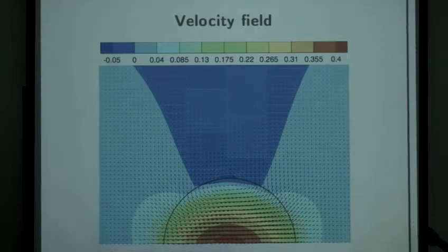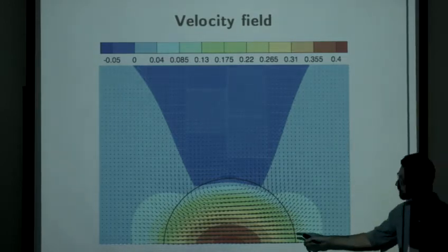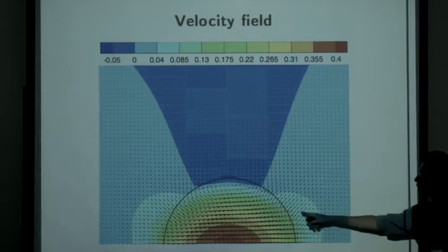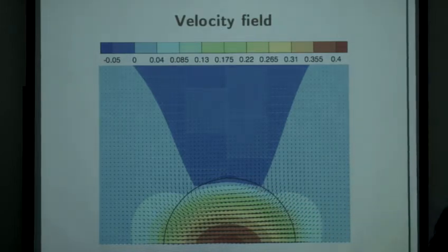The drop is moving. In most cases, I showed the Laplace balance. It's actually the simplest solutions which are the hardest to get. If you have a very complicated flow with all the other stuff happening, nobody knows if it's true or not. If you have something which should be 0, everybody notices if there are little arrows floating around. So what's important here is that you have a nice velocity field, with no little wiggles around the interface or stuff like that.